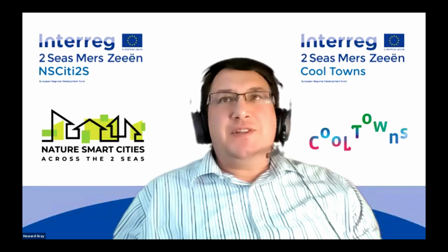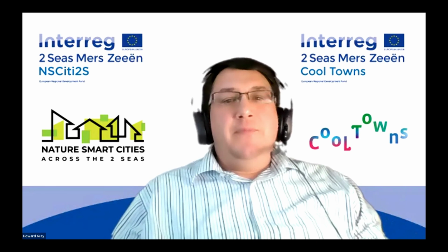Oh, thank you, Matt. Totally agree. Really, when we're choosing a tree species, we have to look at what we are looking to actually achieve from doing so. So you might have a tree that's very good in terms of heat stress, like Matt has referred to, big leaves, but then we get the highway guys who say those leaves block up our drains, so they are looking for something else. So we often have to come to a compromise between what we are actually trying to achieve and what the parameters or limitations are. Also bearing in mind that if we're looking for things like water retention, holding back, attenuating our stormwaters, it's good to have something that's evergreen.